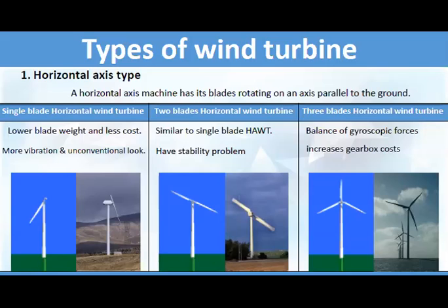Most have a gearbox which turns the slow rotation of the blades into a quicker rotation that is more suitable to drive an electrical generator. Some turbines use a different type of generator suited to slower rotational speed input. These don't need a gearbox and are called direct drive, meaning they couple the rotor directly to the generator with no gearbox in between.